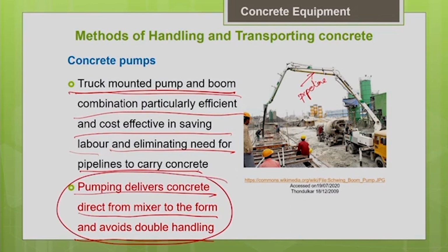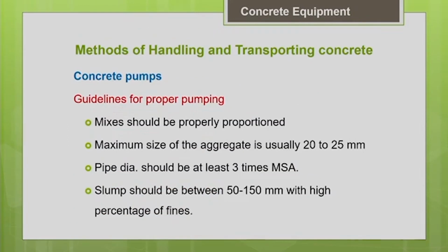Directly you are delivering the concrete from the mixer, the transit mixer or whatever device, directly to the formwork. That way you are avoiding the double handling of the concrete. So there are some guidelines for proper or successful pumping that we should always keep in mind.